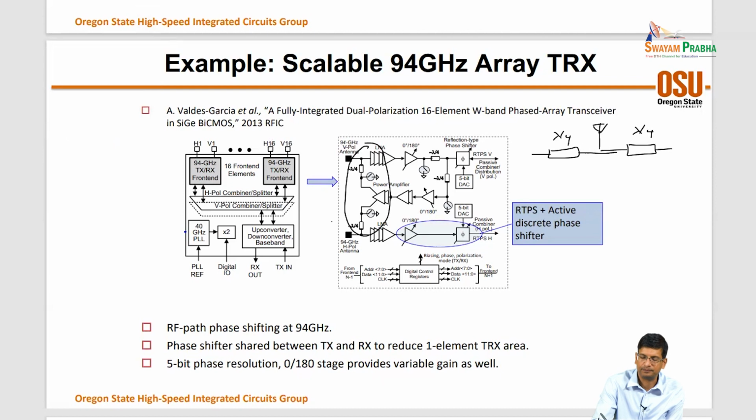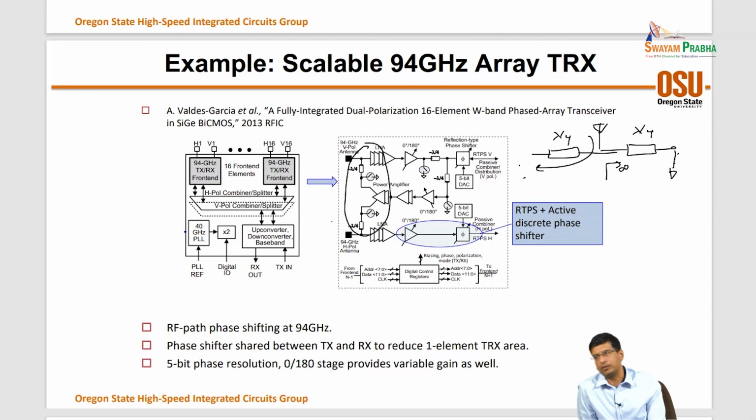And then if let's say this is the RX side, when I'm shorting this to ground, over here I see a high impedance, right? And so the signal goes through and vice versa, right? So this kind of approach gives me good isolation and good loss.